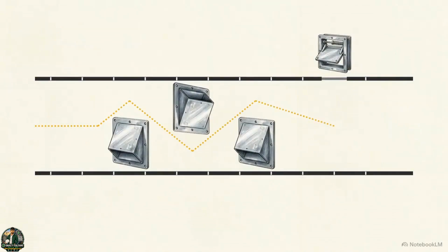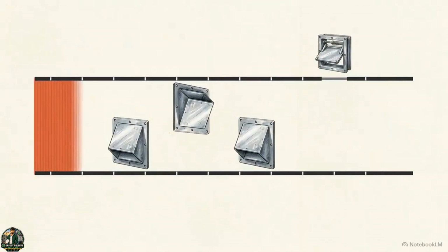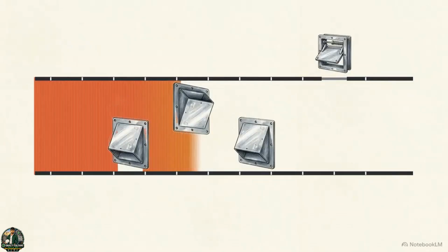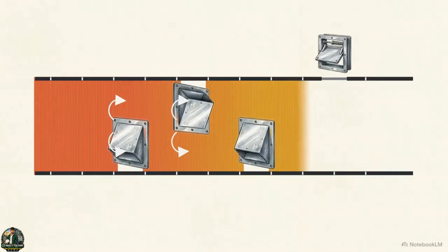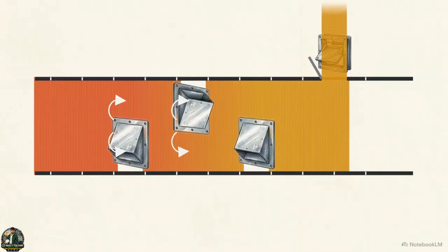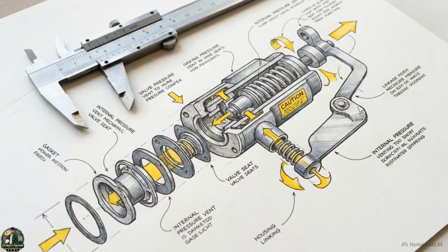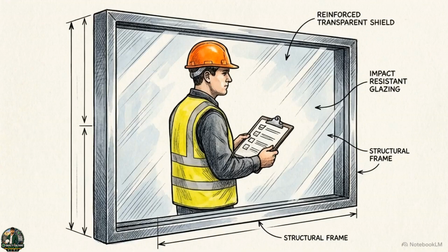Baffles and chokes alter the internal geometry of the pipe. When an internal blast occurs, these staggered barriers force the kinetic energy to change direction repeatedly, deliberately slowing the velocity of the explosion. Once the velocity drops, vents channel the remaining pressure safely out of the system before the kinetic energy can violently rupture the main structural casing. Section 37 forces engineers to embed physical fail-safes directly into the machine's architecture, acknowledging that primary controls will degrade and the surrounding workers need a final layer of protection.